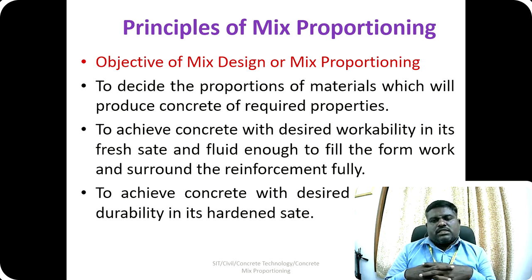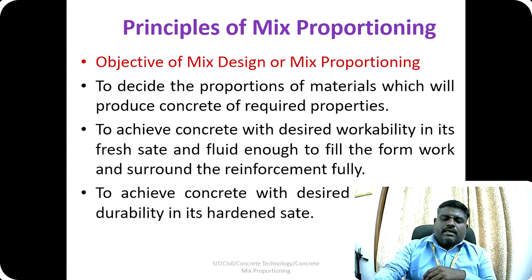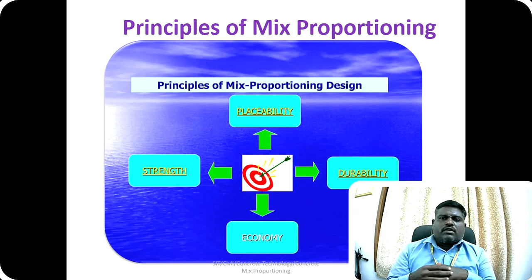And the third objective is to achieve a concrete with desired strength and durability in its hardened state. So after 28 days of curing, the concrete should achieve the desired strength, and the durability should be good when tested for chemical resistance and so on. So these three are the predominant objectives of the mix proportioning of concrete.